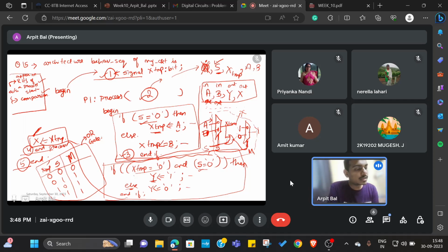So the best way is to use a hardware description language, and it gives you a form of abstraction, right? So instead of actually writing a mux, you can just write it in the form of an if else statement that will also behaviorally represent a mux, right? So there is another form of architecture which is called a structural architecture. So in structural architecture, you can actually define a mux.